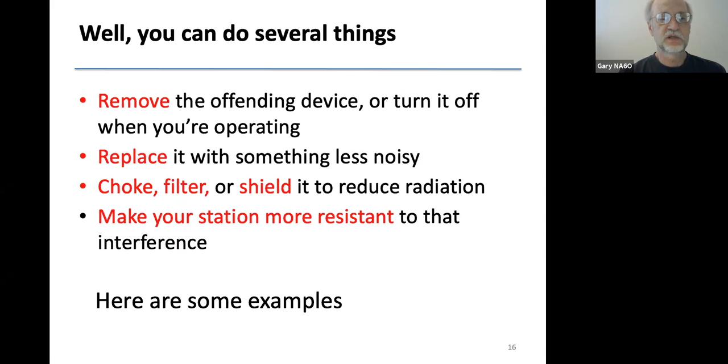replace the device with something less noisy. A good example is I have something that runs on 12 volts DC, and it comes with a wall wart. Well, that's a switching supply, it's noisy. Well, instead, I'm just going to run it off my nice clean 12 volt station supply bus and get rid of that. Or maybe you can find another power supply that's less noisy, or maybe it's a noisy LED light. Maybe you could find one that's quieter.